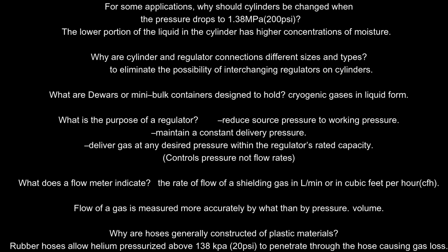Reduce source pressure to working pressure, maintain a constant delivery pressure, deliver gas at any desired pressure within the regulator's rated capacity, controls pressure not flow rates. What does a flow meter indicate? The rate of flow of a shielding gas in L/min or in cubic feet per hour, CFH.